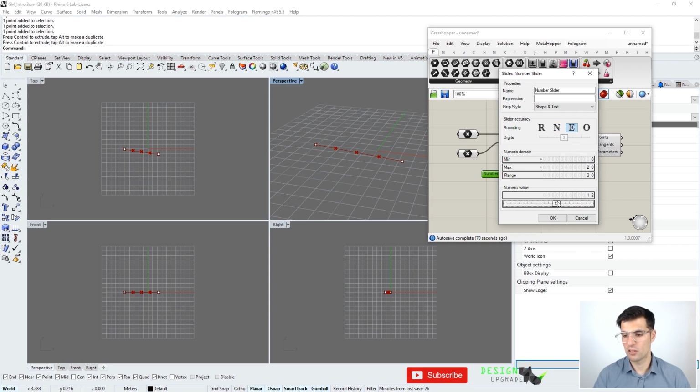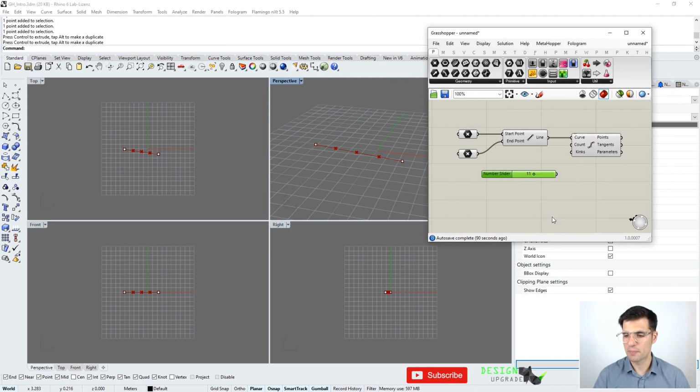And we also have these additional 2 options here, which allow us to create, for instance, even numbers. So now you can see that we are going from 8, 6, 4, and so on. Or we can also select to create just odd numbers, like 5, 7, 9, 11, and so on and so forth. But let's select again the integer number option, and let's get back into Grasshopper by hitting OK. And this is our modified slider, and you can see that now we are creating just integer numbers.